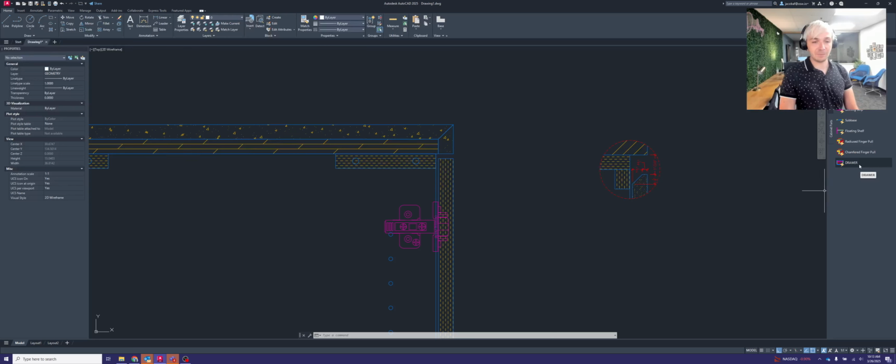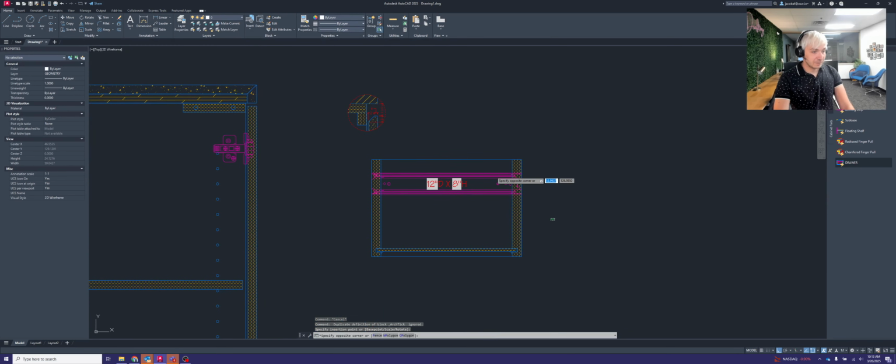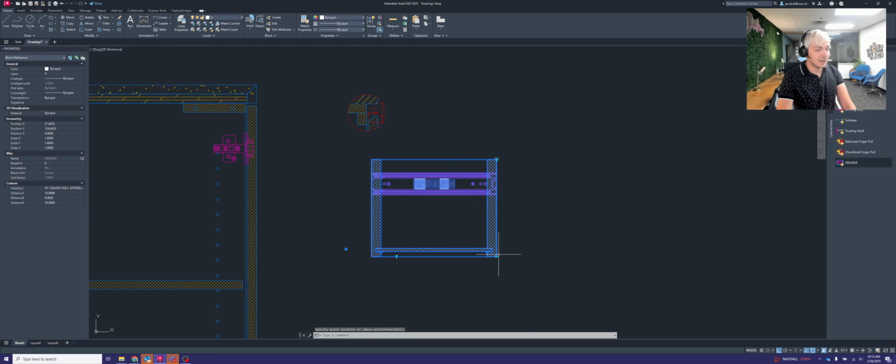Last thing on this cabinet components part is the drawer boxes. So drawer boxes have a block here. These blocks are adjustable, just like the other cabinet blocks. They have 2-inch increments built in, limiting it to 28 inches by 10 inches wide or deep. They also have height adjustments here. Generally, you want to stay within 1 inch. So like 8 inches, 9 inches, 10 inches. You don't really want to go like 9 3/4 or 10 1/4 or something like that. You want to make this as simple as you can. So we'll make it a 1-inch increment there.